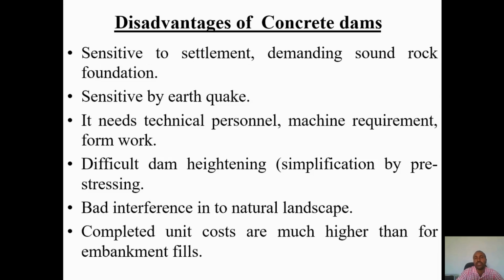But the disadvantages of concrete dams: they are sensitive to settlement because of their heavy weight, so they demand a sound rock foundation. As I have said earlier, you need a sound rock foundation. They are sensitive to settlement and also sensitive to earthquakes.